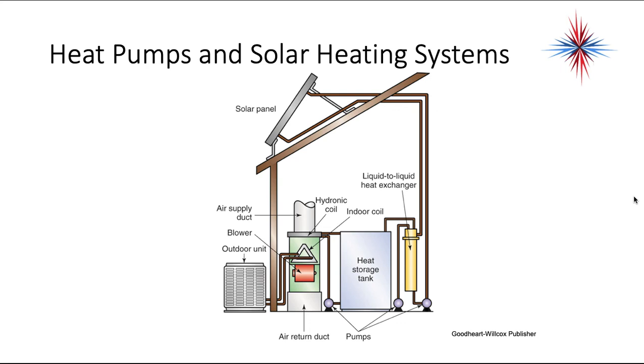That can also be used as auxiliary heat in the defrost cycle, because again, remember, when we use reverse cycle defrost, we're all of a sudden making that indoor coil cold, and we're making the outdoor unit the warm coil. So people can feel a cold draft when a system is in defrost. That's why auxiliary heat is required.